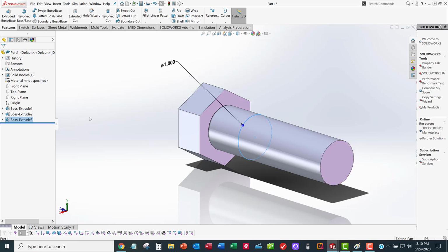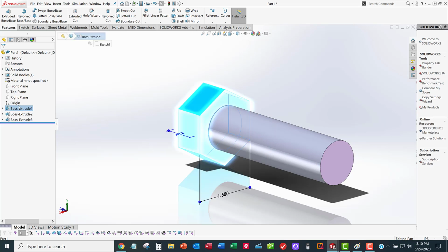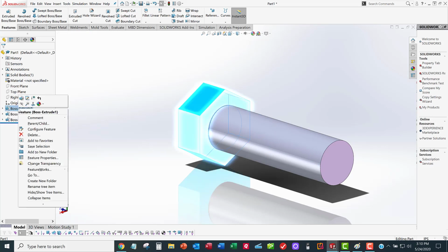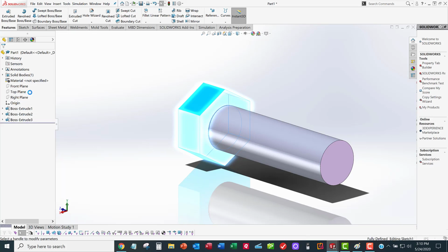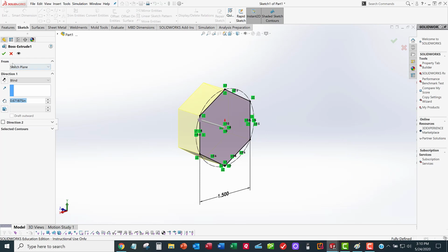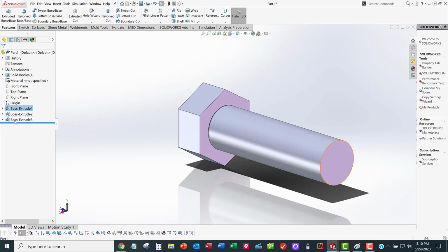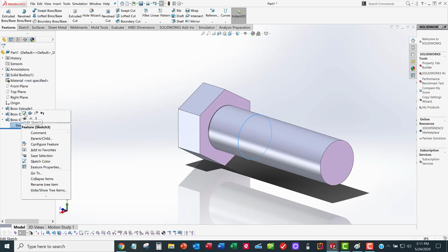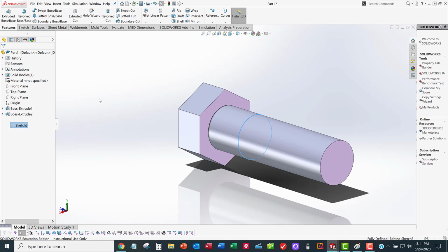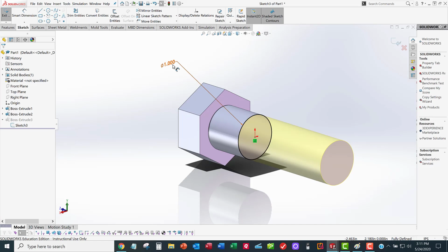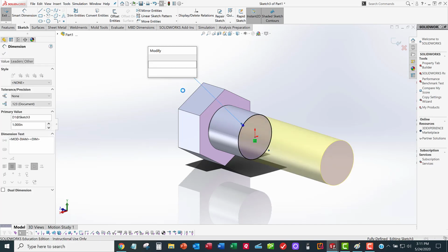To get back into it, if you want to edit one of the features, just select the feature and right click on it and go to Edit Feature. You'll be able to change the parameters of the depth of the extrude. If you want to change the sketch, go find the feature, open it up in the tree, there's the sketch, right click, and then say Edit Sketch. Right click will get you options. That'll almost always work. Now what if I make this one maybe 0.995.